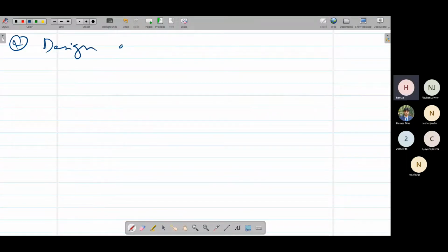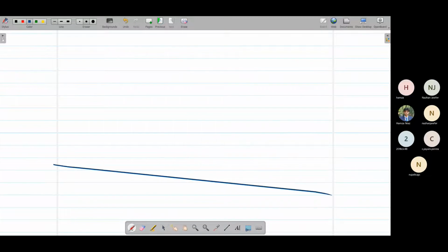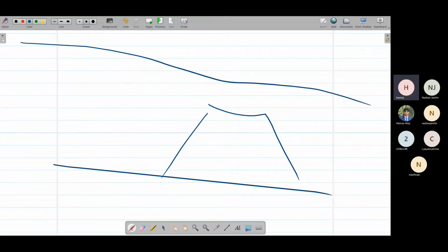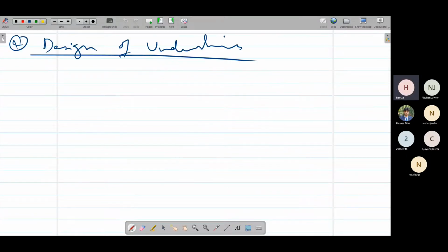So this is very much similar to the before one. Just a little bit of difference is there. But if I draw this diagram again, this is our weir and this is our flow value. So for undersluices, we are assuming the crest level of undersluices is 3 feet below the original crest level. So the crest level of weir minus 3 feet. We are assuming this ourselves.